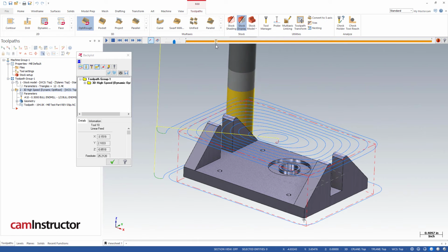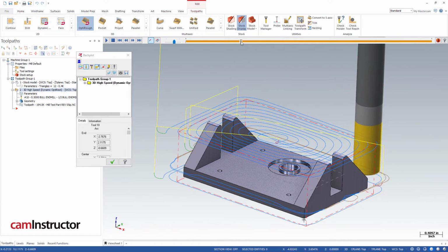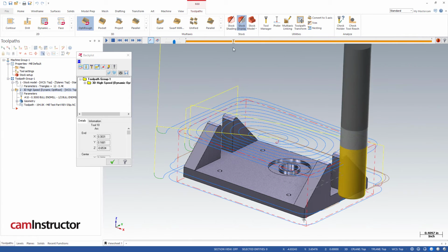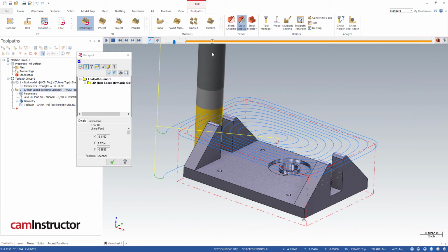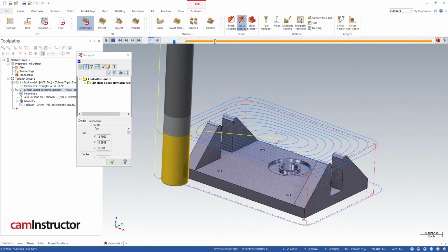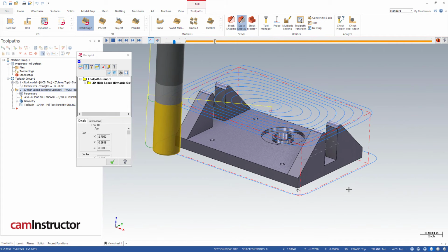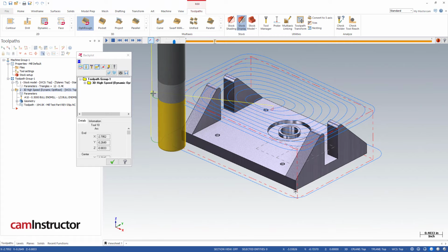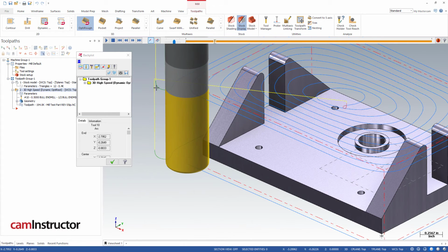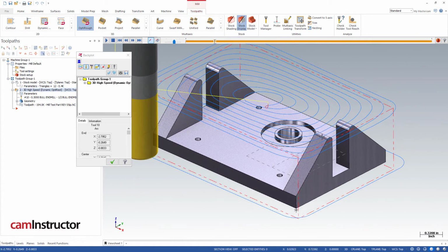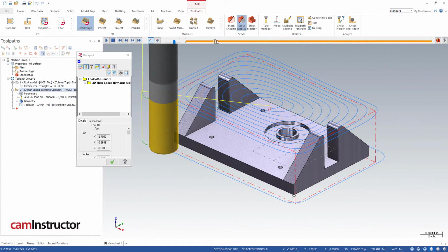Let's look out for some more toolpath motion here and see if we see anything else that's not great. Let me just back up here for a second. Notice this path right there. In my toolpath display here, any cutting motion is going to be blue. Retracts are yellow. Feed-ins are green. Lead-outs are red. And I believe transition values will be a brownish color.